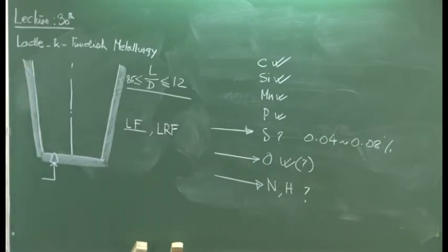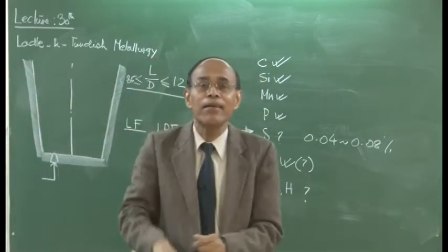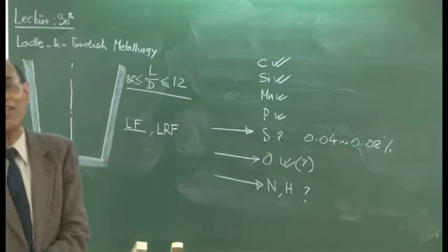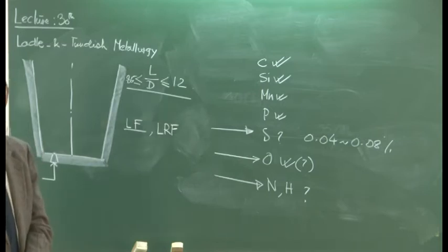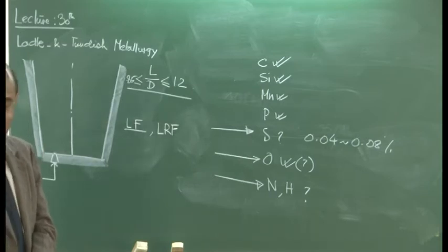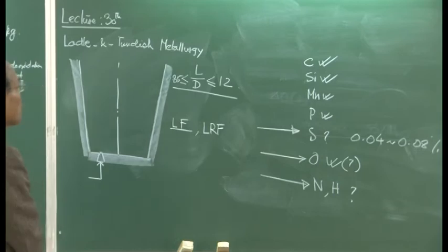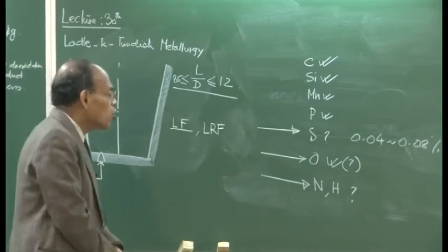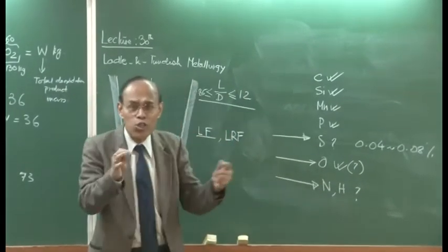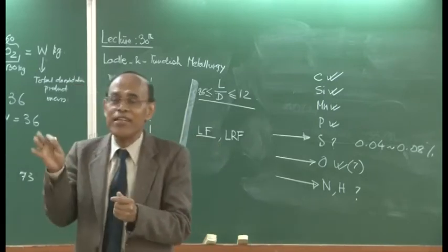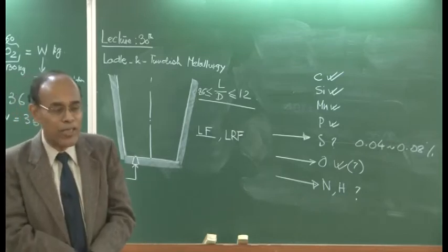Also, we have noted that we may have carried out steel making at 1600 degrees centigrade, but the temperature has gone down to a significant level during the tapping operation itself, because of the simple fact that at high temperature, 1873 Kelvin, you have enormous amount of radiation losses from the surface. So, if you have carried out the tapping operation for 10 to 15 minutes, there could be a 60 to 70 degree drop in temperature. Now, to eliminate sulfur, to adjust oxygen, to eliminate nitrogen and hydrogen, and also, as I have indicated, topics like calcium injection etc. to enhance inclusion flotation, we have to give some time.